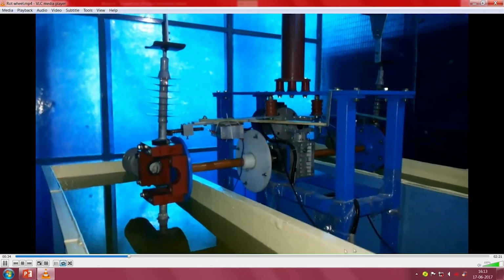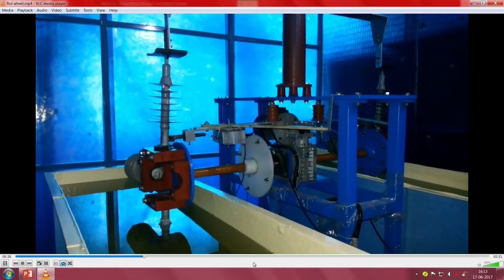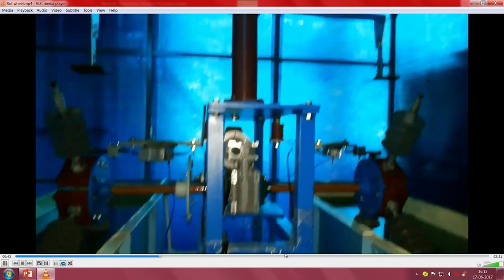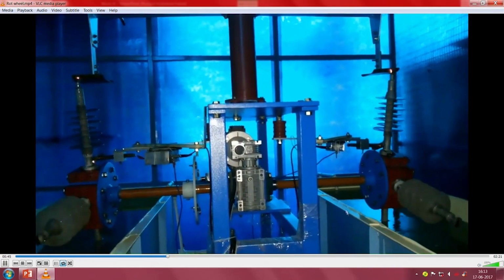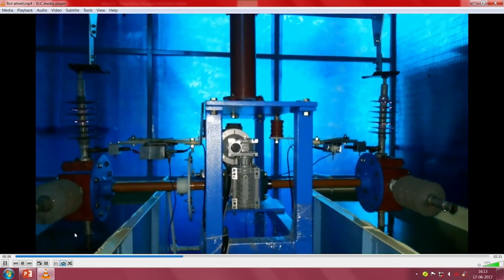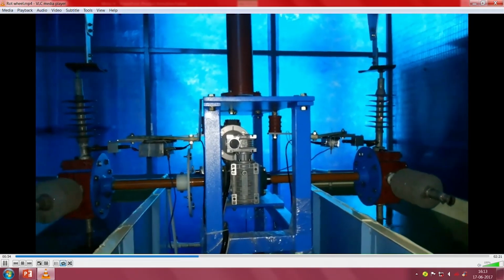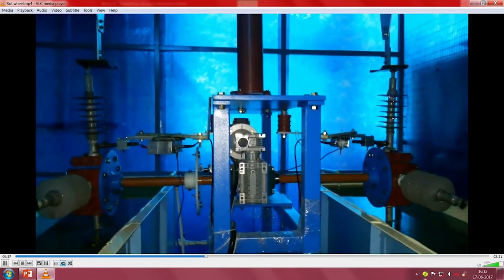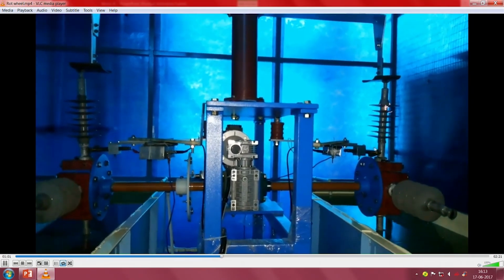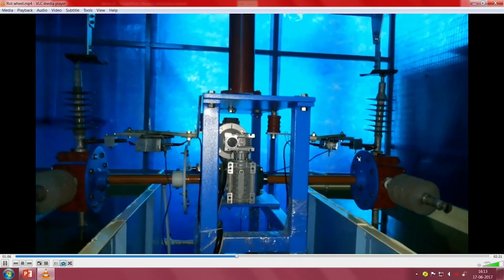So, one is a normal contaminant, the other is an acidic contaminant. The activity of the insulator, or the surface activity because of electric stress, is very clearly seen. So, this cycle of rotation and the voltage stress will be continuously applied for 1000 hours, and the experimentation is being conducted. During the experimentation, the flow of leakage current on both sides is measured using the shunt box